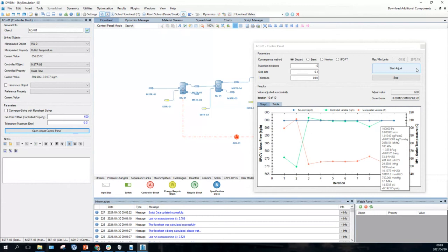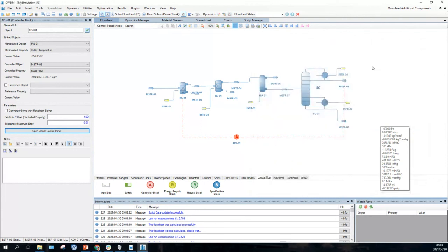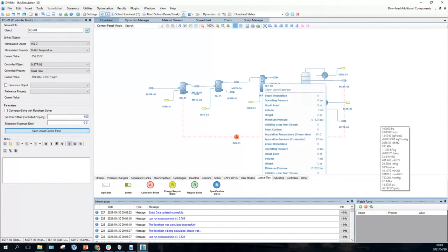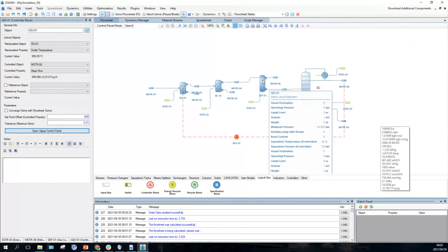Not so difficult. As I say, if you look at this process flow diagram, let me get back to this control panel, close it. You can see we've used these principles of process creation that you were tested on in the test. There we had a reactor. We've got all of the reaction products. We cool it down to 40 degrees C, and that is heuristic number 9 according to the numbering of the heuristics in our class notes.